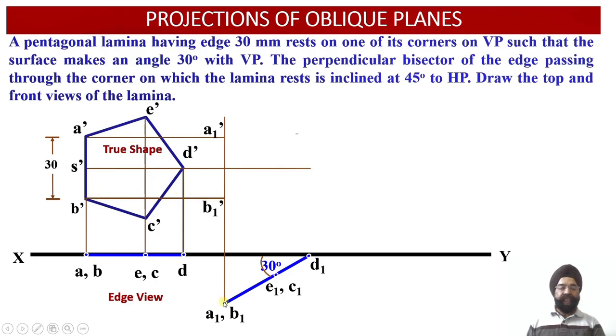So now we can see, once we draw the vertical projector in the upward direction from the point A1, now we have to extend this vertical projector in such a way that it should be intersecting with the horizontal projector which has been drawn from the point A dash. So this intersection provides us with the location of the point A1 dash.